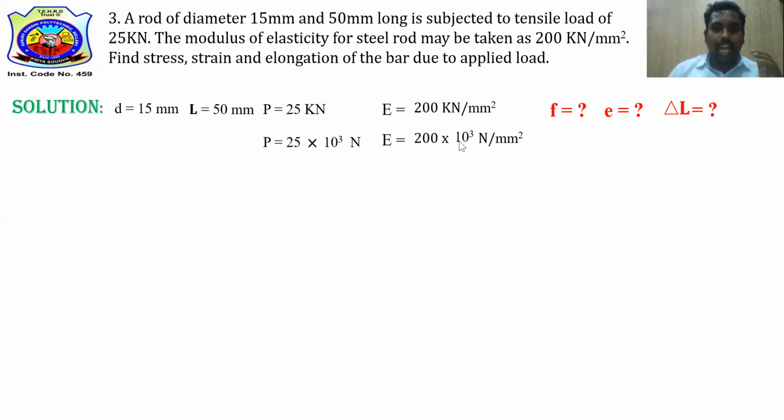Okay, done. So as I said, there are a few steps we need to follow. That is area, stress, strain, Young's modulus, lateral strain, and engineering constants, step by step. First, I'll do the area. Area formula is A equals pi by 4 into d square. First check how many unknown values are there. A is unknown, yes. Pi by 4 is a constant value. What about diameter? It is given. So we have only one unknown value, so we can solve for area.